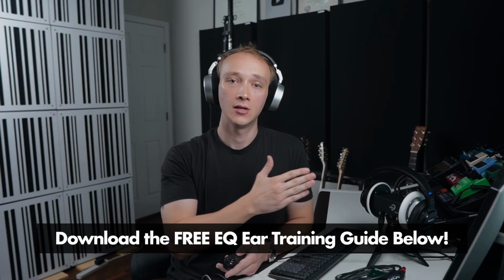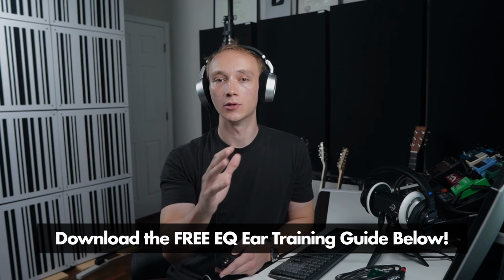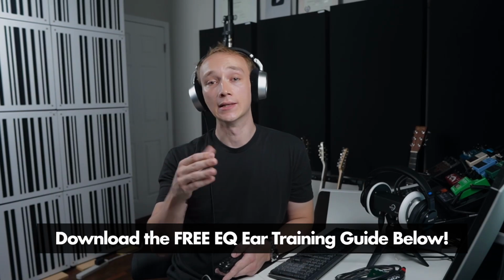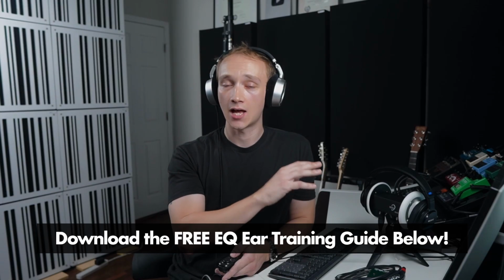The human voice doesn't have much energy in the lowest frequencies anyway, so engaging the high-pass filter allows us to clean up low frequencies without impacting the tone of the vocal itself. This can be especially useful in live sound when microphone feedback at lower frequencies is a common obstacle.